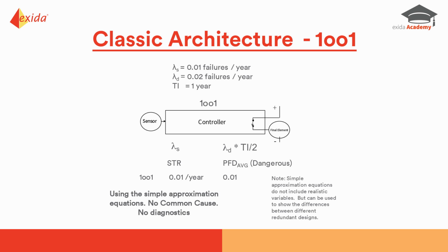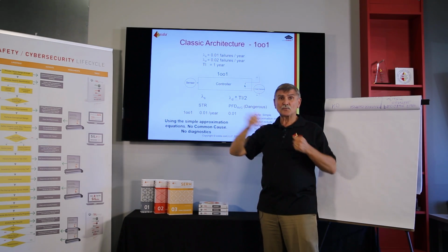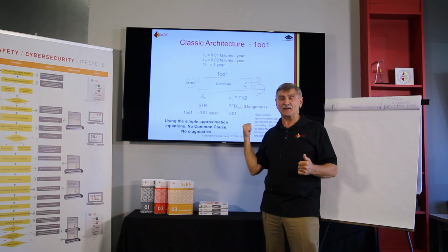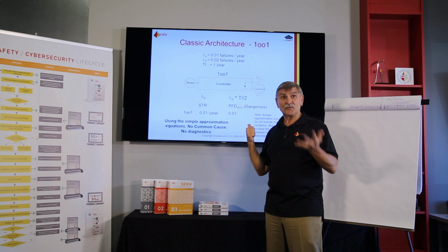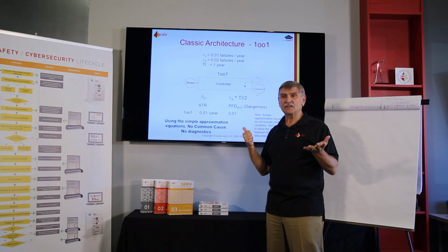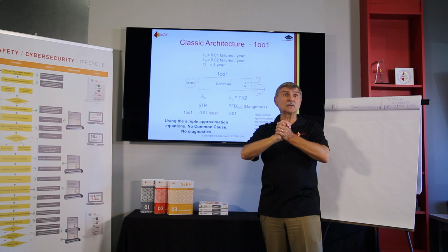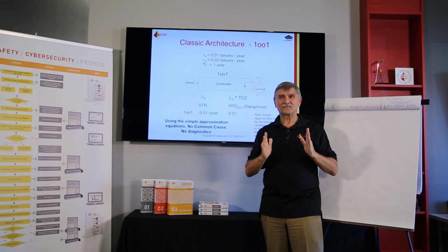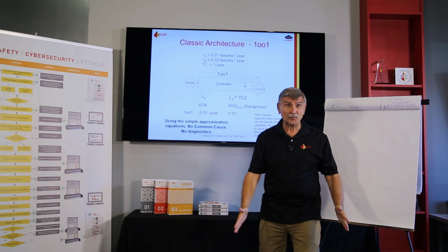If this controller runs properly and there's a demand, the switch will open circuit, de-energizing the final element. Make sense? If there is no dangerous condition, the sensor says everything's okay, switch closes, and the final element is energized. Energized, okay. De-energized, trip.